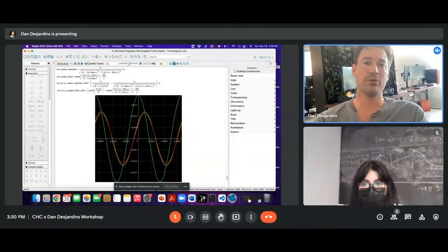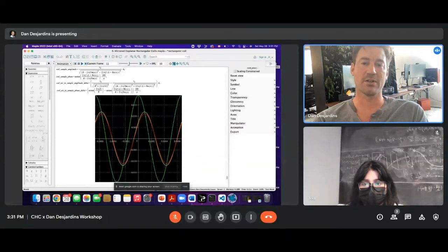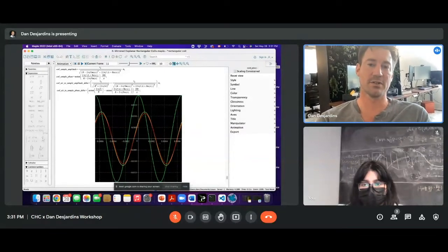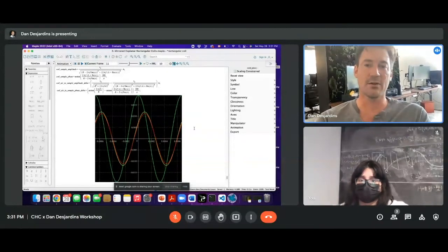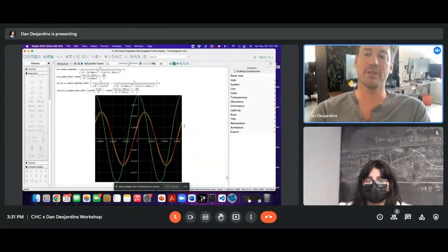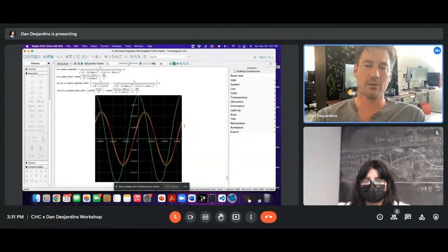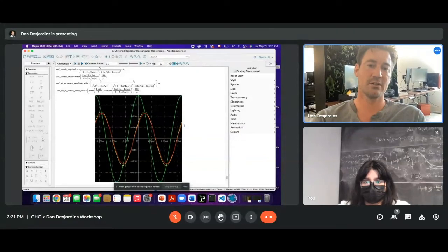So the green signal here is the voltage. The yellow is the current, and you can see the current is lagging the voltage because of the self-inductance of the coils themselves. And then the red line is the coils next to a plate. So clearly the presence of the plate is modifying the shape of the signal. So that's the sensing going on right now. She collects experimental data by taking her air core coils and putting them next to the plate, and it matches. Well, Bob's your uncle.